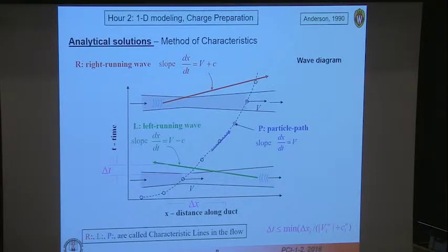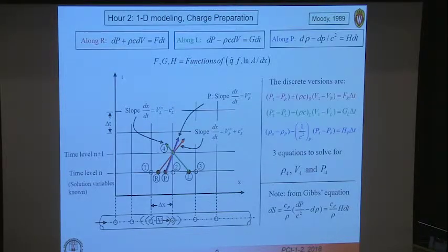Courant-Friedrichs-Lewy condition, the CFL condition. So that's just something to bear in mind, and it's very interesting to understand the physics behind that: sound waves are propagating in our compressible flow that are basically informing each fluid particle about the conditions upstream and downstream of their location.